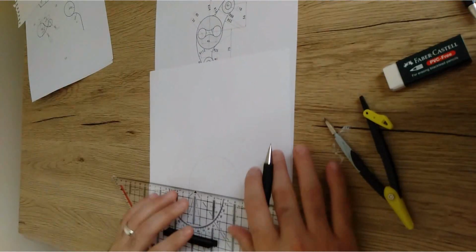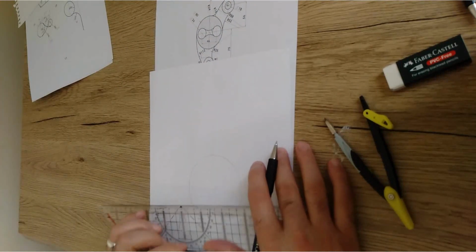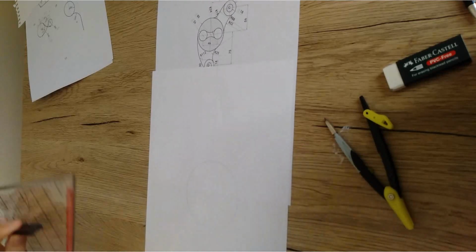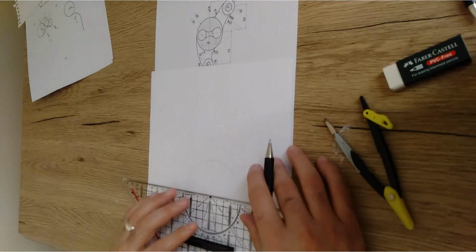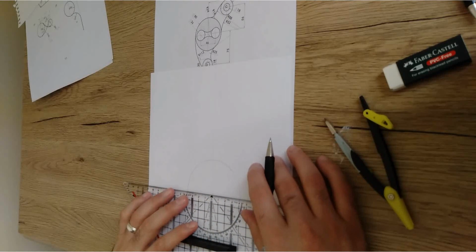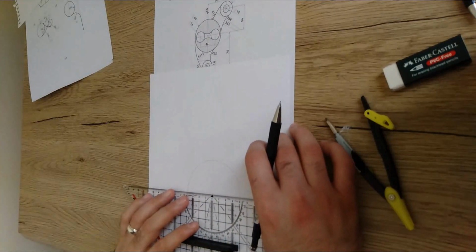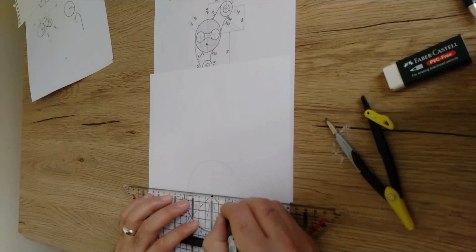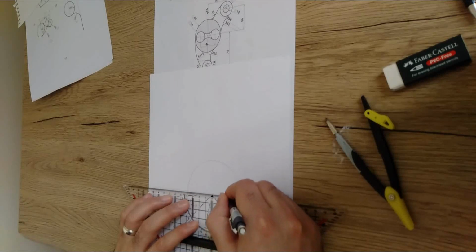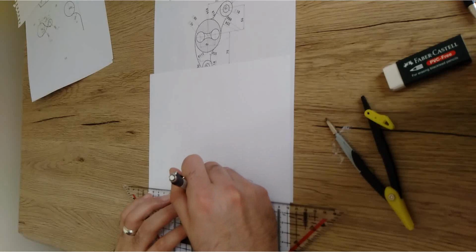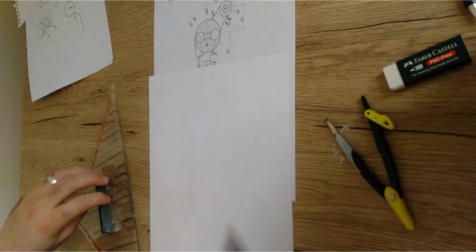It means that you have to make sure that you do have this horizontal line of the circle already located, which is this one. Over this one, I'm just gonna measure 46 over 2, which is 23. So I'm just gonna measure 23 from the right and mark a point. This should be the center of the right circle, and another 23 from the left. So I got the two centers.